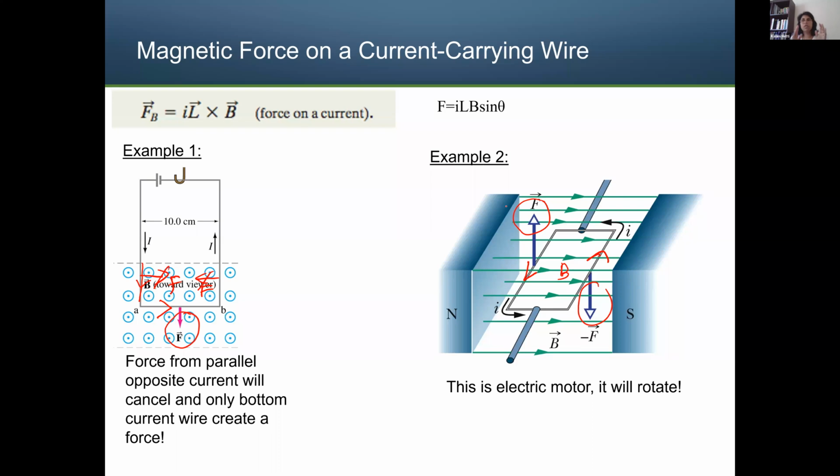So now this will not keep rotating. What will happen is these two coils stay like this. Then they're going to rotate in this direction. When they rotate in this direction, then it will be parallel to your magnetic field lines. Then there is no force acting on any of the turns of the coil. Then you need external force from outside, by using magnets or by using AC current, you can switch the direction. Whichever way we are doing externally will help you rotate this back and forth. That's how the electric motors will work.